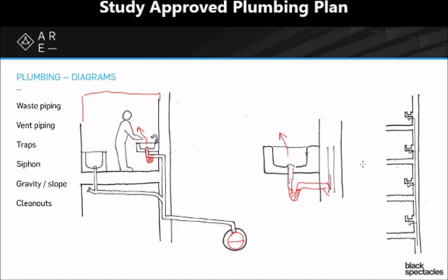One of the drawbacks is, if I have a whole series of sinks or toilets or whatever, one floor after another, if you imagine that, say this sink fills up and you're washing dishes or doing something, and now you're going to let all that water go, and it's going to go rushing down that pipe as it goes down that wall. Well, there's air in front of it and there's air behind it, right? There's only so much water that's filling that pipe, but it's going to fill the pipe up.